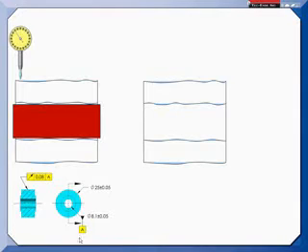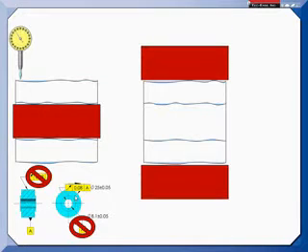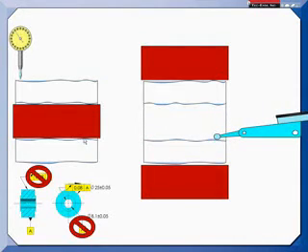But let's say that we switch these around. We make the outside diameter the datum feature, and then we put the runout on that hole because that's what the supplier would like to see. Well, I close in then on that outside diameter, and you notice I'm only hitting the high points. I ignore the low points that the indicator picked up that my design is probably interested in. And then I'm going to come in with an indicator and do the runout check, which is going to look at the highs and lows in here when I'm really concerned about how the highs are contacting that stud, that mating part. The lows aren't as critical.